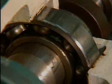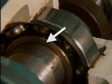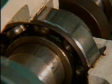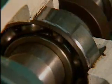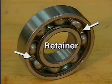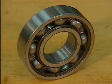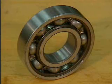In a typical installation, the outer ring is fixed and doesn't move. The inner ring is fitted to the shaft. As the shaft rotates, the inner ring also rotates. The rolling elements are held in position by the retainer, which you may hear referred to as a separator or a cage. The retainer positions the rolling elements evenly around the rings and ensures that the load is distributed equally on each rolling element when the shaft is turning.